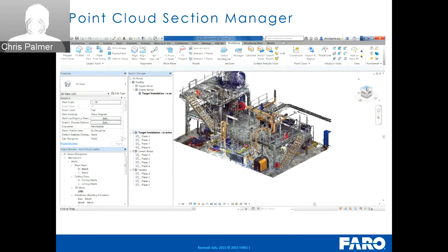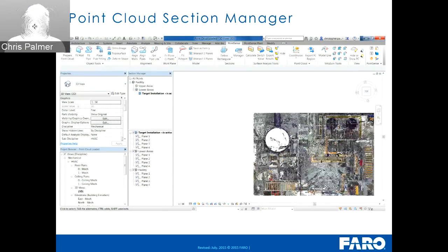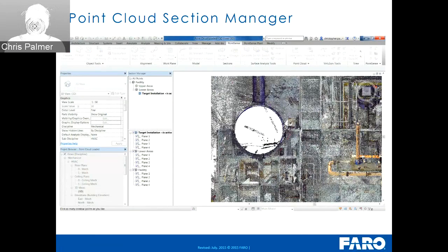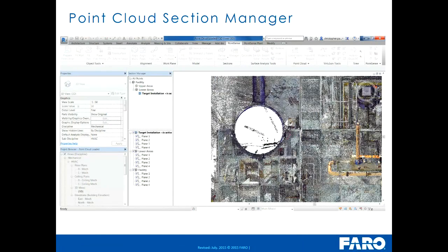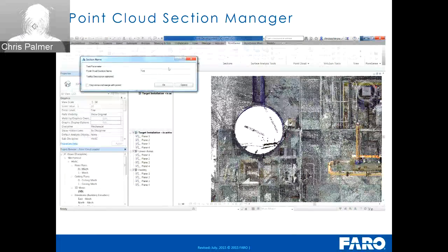I'll drop this into a top view and zoom in a little bit. If we want to isolate a specific area, it's sometimes easier to use a polygon selection. So if we go to the define polygon tool, I'm literally going to click around the outside of this now to define the tank. As we work our way around, if I press the escape key, it's just going to isolate out that tank. We give that a name, so we'll call this tank.